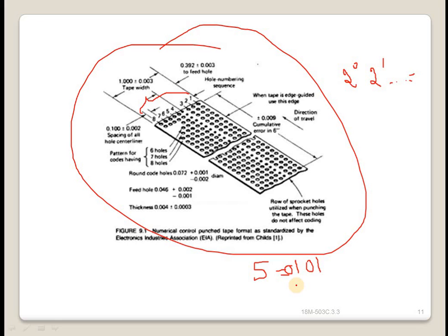Next, feed rate and cutting speed. They specify the cutting speed of the process, the rate at which the spindle rotates. Units are revolutions per minute. In a machining operation, it is usually desirable for the tool engineer to specify the speed in terms of the relative surface speed of the tool and work. Tool selection: this would only be needed for machines with a tool turret or automatic tool changer. Miscellaneous functions,